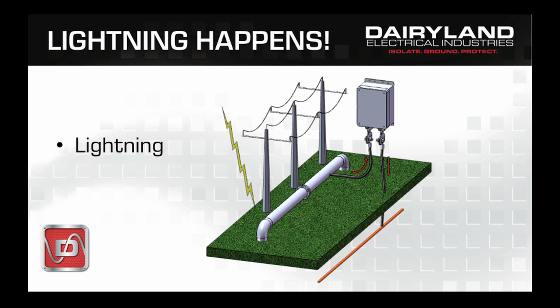Let's talk about one of the most common faults that a decoupler must protect against, and that's lightning. In the event of a direct lightning hit to a structure that is protected by a decoupler, we must safely pass that lightning current through the decoupler to the grounding system. This is done to not only protect the structure, but also help protect any workers that may be in contact with that structure. Additional measures can be taken to help protect workers, such as gradient control mats, but that topic will be left to another video.